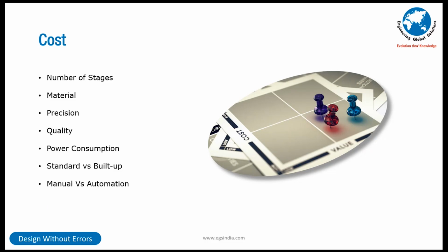So if I increase the number of stages, then my thinning can be controlled because of strain rate. It is an additional cost, no doubt about it. You're incurring a cost, but look at your durability expense when the problem is reported by your customer in the field, and the customer happens to be sitting in Japan or in the US, and you have to airlift a component to replace the shipment, and he's asking you to come over there to do a 100% inspection.